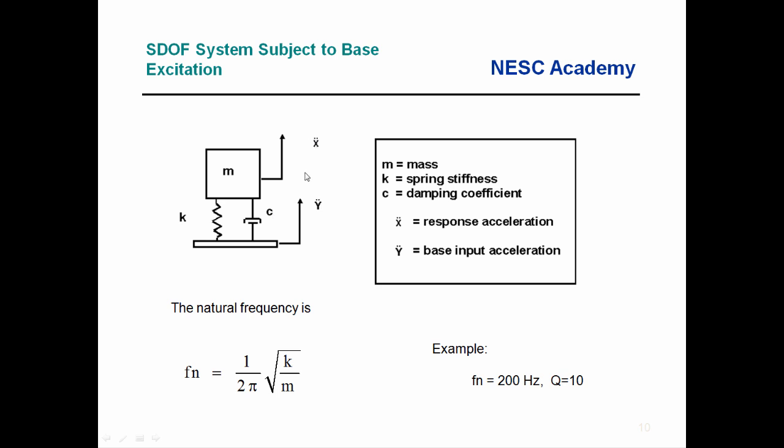Now in previous units we've gone through the process of taking the system, drawing a free body diagram, and using Newton's laws to sum the forces and set that equal to mass times acceleration. We also found that in terms of applying the base input in the time domain, after a number of steps we could derive what we call the Smallwood ramp invariant digital recursive filtering relationship.